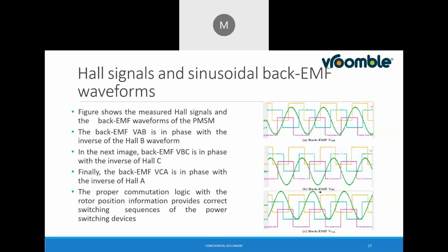to provide the right feedback to the controller, because there will be a demand from the rider or the driver as a throttle input, and that has to be converted in terms of the current, which eventually will be converted in terms of the on and off frequency, and that will be converted as an AC current to the motor to drive the motor or to rotate the motor, right?